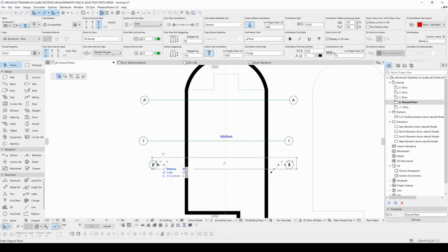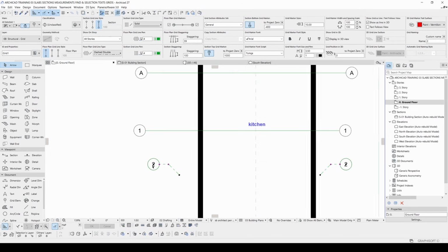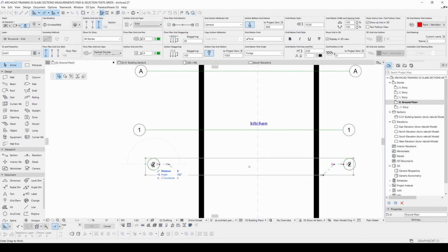You can edit the grid by using these points. You will click these purple points. And if you hit the Shift, you will see this flux to that X direction. And you can use the Shift for many commands such as placing walls, slabs, lines, and most elements. And I'm hitting the Shift and clicking this point, and they will be exactly on the same point on the x-axis.